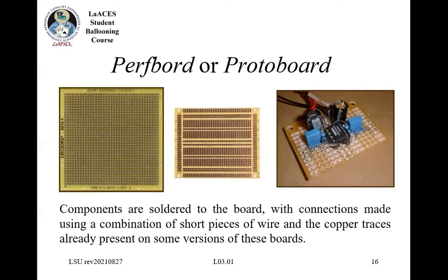We'll keep moving across. This is not a layout. This is a step up from the breadboard, and these are called perf boards or proto boards. There are a lot of different types, and a lot of them have very different connections, so you can look at that when you're starting out. This will allow you to make solder connections. It's a little bit more permanent than the breadboard, but it still can be a pain. Sometimes, though, this is really quick and easy to get something implemented.